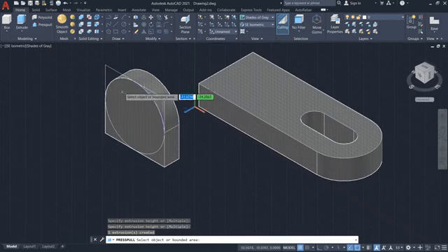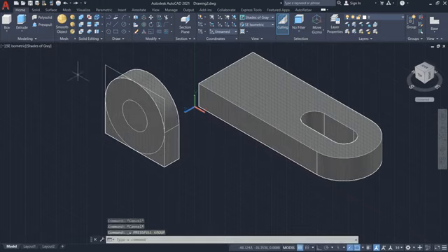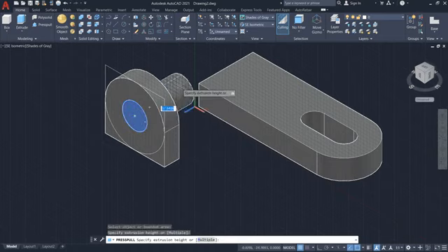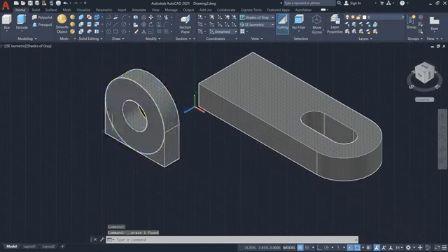Now I will draw the inner circle whose diameter is 20. First of all I will snap the center. Now I will enter the radius. Radius will be 10. Now I will delete the inner circle. Select press and pull, and remember for press and pull you have to select the inner surface, not the edges. I will select this surface and go inward. Okay, I have deleted. So now I will delete this portion also, and this circle outline.